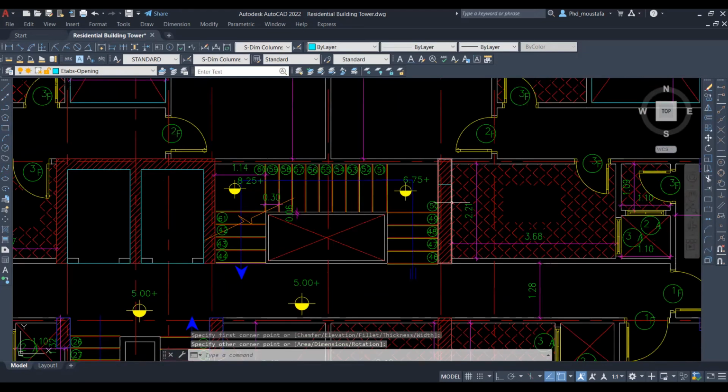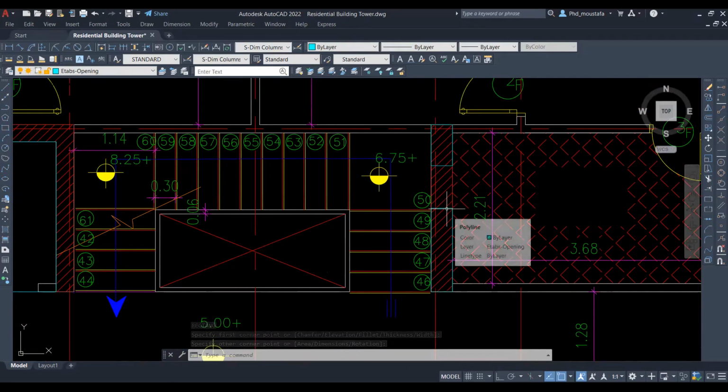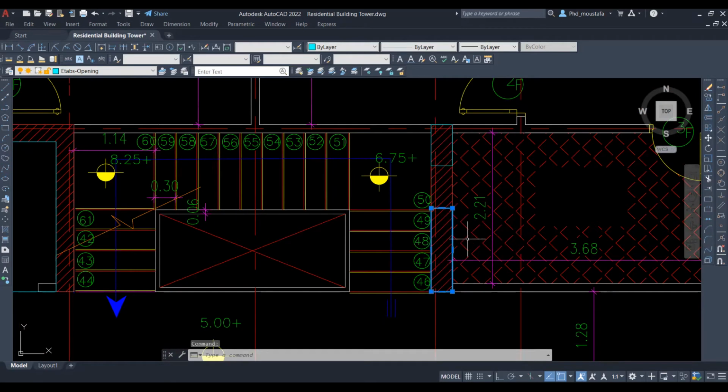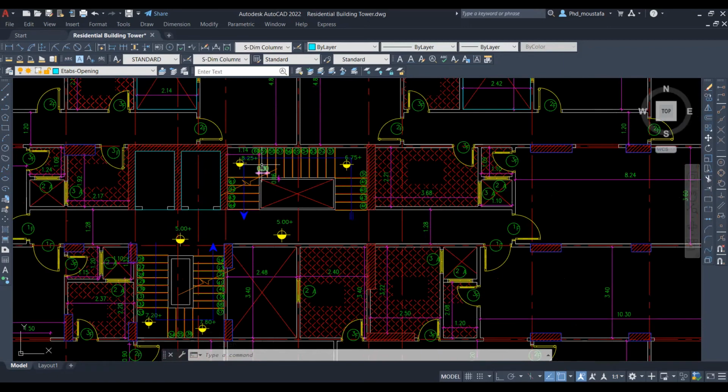This can be another type of design if the architect accepts. But I agree, and no problem to keep the wall instead of 2 columns. As a high-rise building, shear walls are needed. Maybe 10-story towers are considered high-rise buildings.